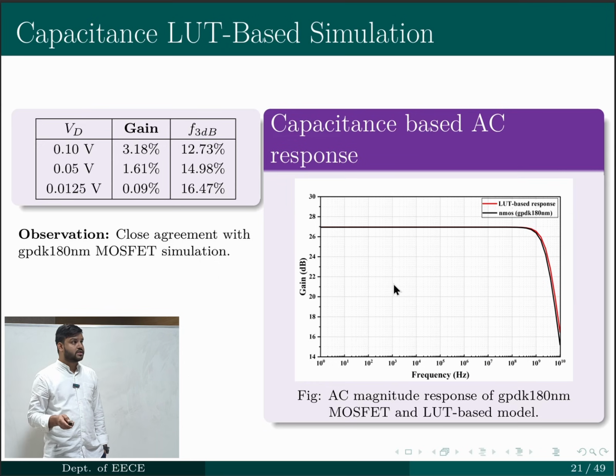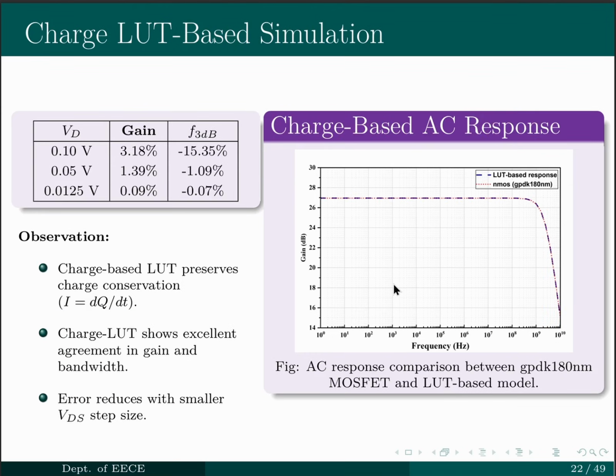So it was also tested with the charge based LUT, which shows that for the same step size of VD, there is similar behavior in the gain, but a good improvement in the bandwidth. The plot also shows close agreement between the LUT and the GPDK NMOS.